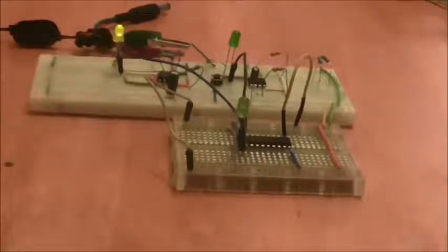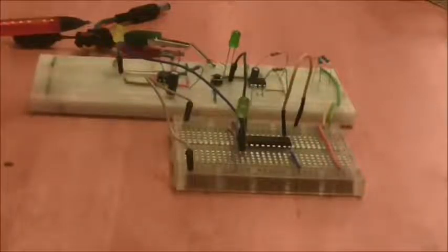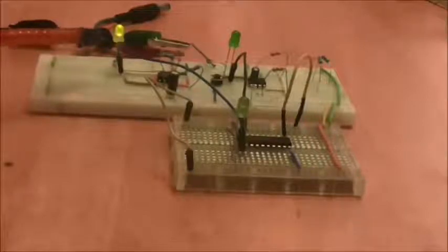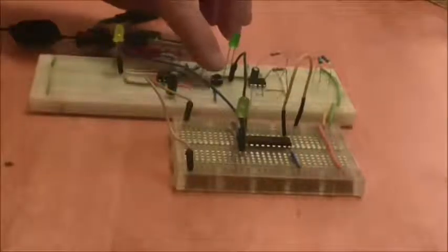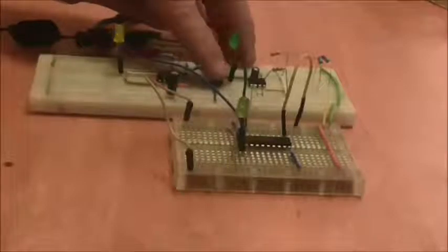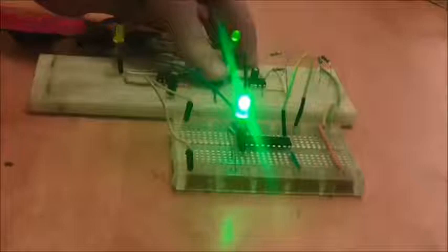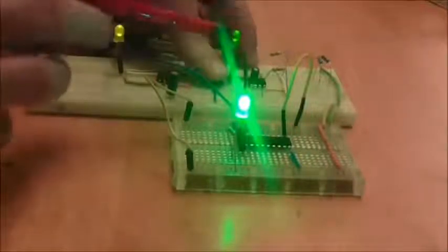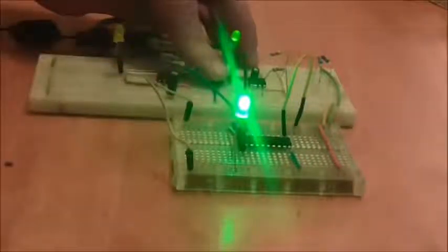Now, this yellow LED is measuring the state of the clock. So, the clock is high when the LED is lit and low when the LED is dark. And what we're going to do is wait for the clock pulse to go low and press the button to trigger the monostable. And you'll see that as I do that, it doesn't matter what the clock is doing, as long as there's a positive signal here from the monostable, this LED shines. And as I let the button go,